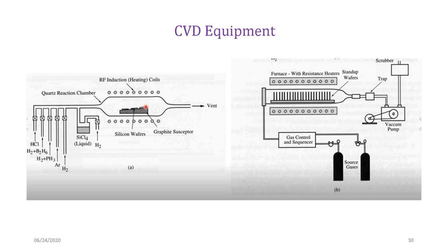Here also you use at least two different kinds of pumps. But you can also have an atmospheric pressure chemical vapor deposition equipment where we do not need a turbo pump at all. So it depends on what material you are depositing, what kind of precursor material it is going to be, and how harmful or harmless the whole process is going to be, and depending on which you can either design very low pressure equipment or equipment that functions at atmospheric pressure as well.